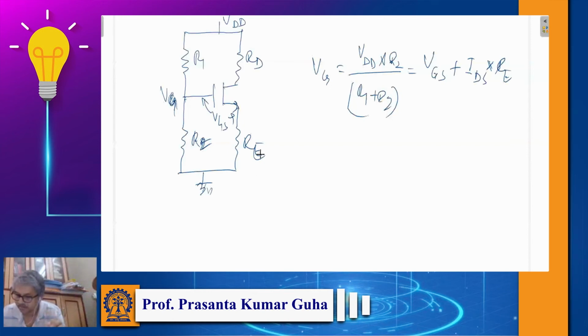When we discuss the amplifier part, we will see that this Re will reduce the gain. If Re reduces the gain, what we usually do, you remember, is apply a capacitor here to bypass this resistor fully or partially, so that the DC only sees this resistor, but the AC signal will not see it. The AC signal will see a short and pass through that capacitor. We will discuss that when we go through the amplifier part, but just for completion of the discussion, we can use a resistor, but partially or fully bypass it as far as the AC signal is concerned.